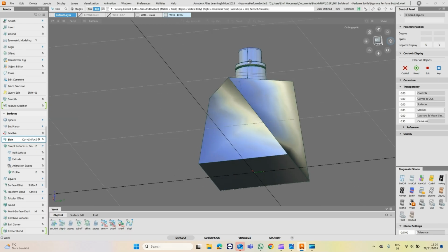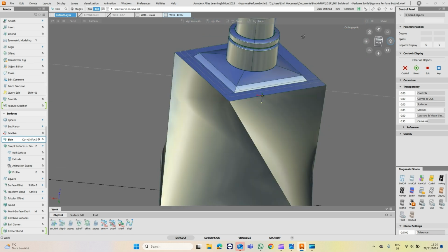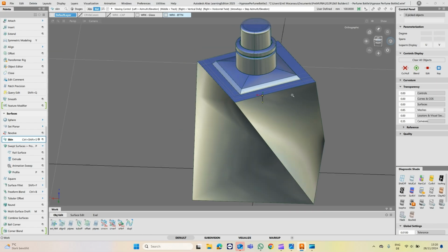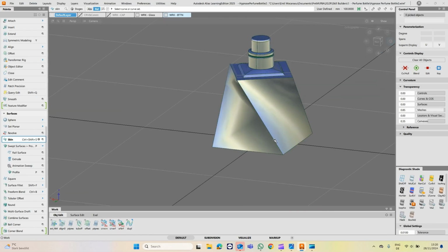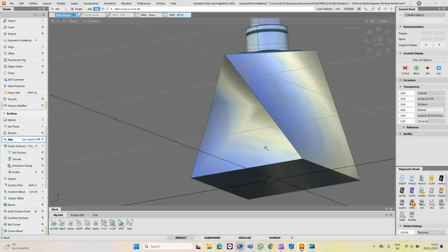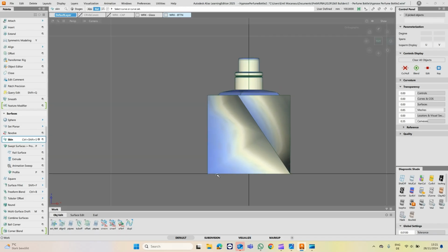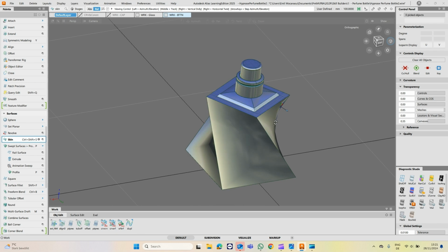Make sure you save, because we are now going into the final details there. And most of the times those final details are the ones which will be ruining the fun, meaning radii. That's it, we have to do them. So that's saved up. We will be running the bigger radii here at the bottom. Around here we will be having quite sharp ones, here bigger ones as well. So first run the big ones and then the smaller ones.